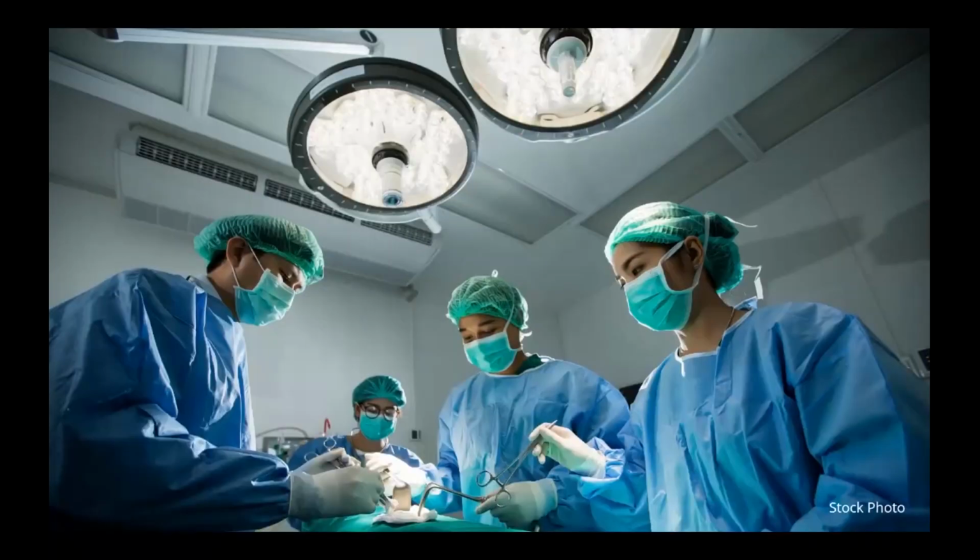So here we see another operating room space. And right away, we see up at the ceiling what looks to be, because we have piping coming out of the wall, this must be either VRF or some kind of fan coil. Either way, it's not ASHRAE 170 compliant. It's not a laminar flow diffuser. And honestly, anything that's involving the exchange of humidity and possible condensation sources within an operating space is going to be a potential source of pathogens.